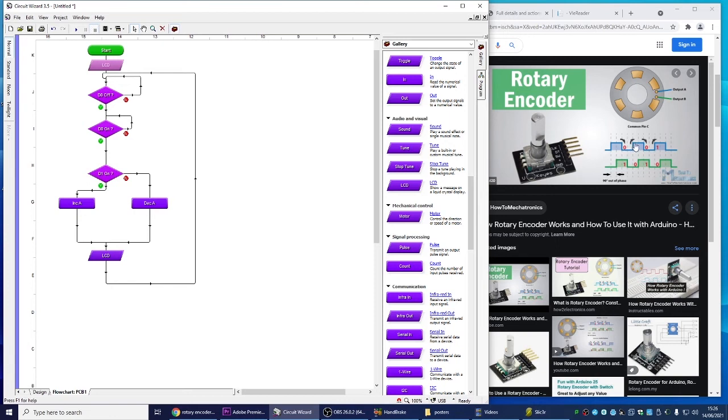At that point, if input B, D1 is off, let's say this is increment, so if D1 is off, well in this case it's decrement. If it's risen up on this edge, so it's been turned the other direction, D1 is going to be on at that point, so we'll know to increment in this case, get the right way around. But whichever way, you can trial and error it and then swap increment or decrement round. And that's pretty much it. That's how this thing works. So let's just see if that works.